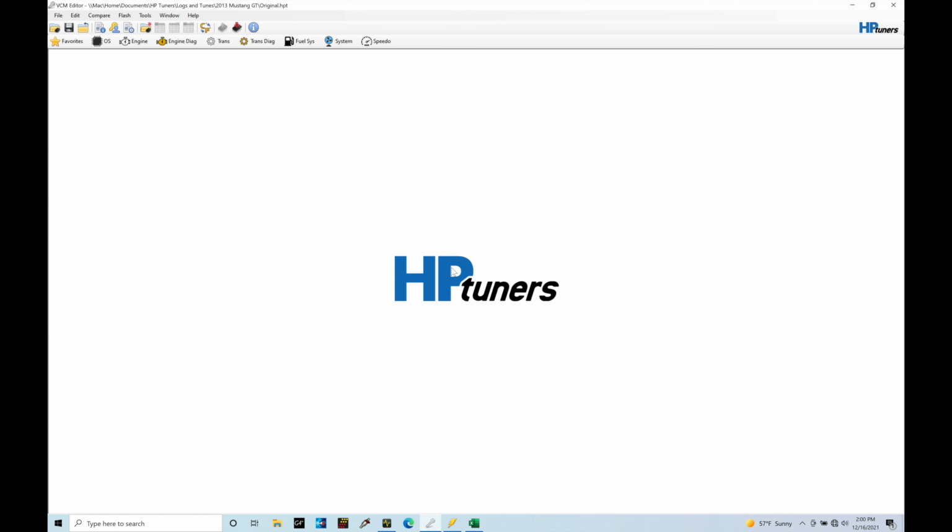Okay, so let's get started. We're going to be taking a look at programming our fuel injector characterization data based on aftermarket injectors we might be installing into our fuel system for our Gen 1 Ford Coyote applications. We're going to be taking a look at the importance of our injector data and making sure that everything is done properly when we're going from an Excel sheet that's provided from the injector manufacturer, the data sheet, putting all the injector data into the actual calibration tables of where it needs to go.